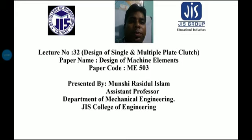Otherwise, the plate would wear out if the friction is high. So for that case, we consider some design considerations based on different fundamental points. The power and torque transmitted through the clutch must be accurately known. Number two, suitable friction material with proper friction lining and proper friction properties must be chosen.